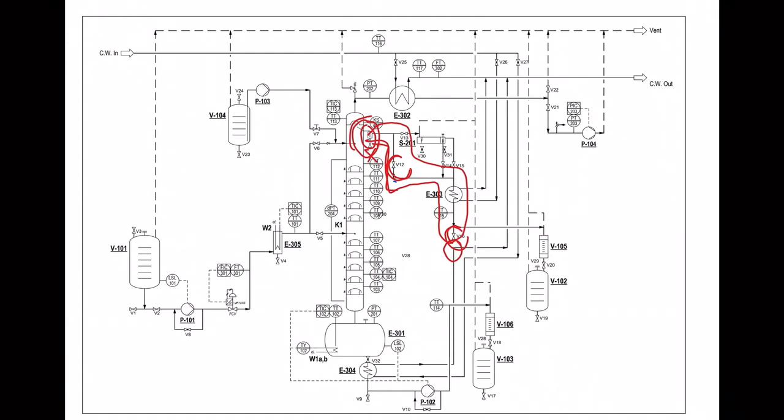For the bottom sampling, you place a beaker below the valve V9. Then slightly open valve V32 to allow the liquid to flow through the bottom cooler, which is E304. Then you close back the V32. Open valve V29 after you collect enough sample, then close back valve V9.